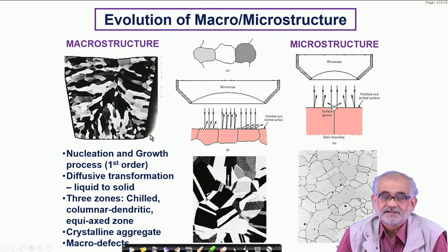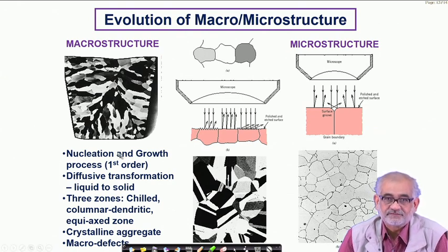And this hierarchy tells us that a given system like this may comprise a single or multiple phases, and also may comprise a single crystal in very, very rare cases where we create an artificial condition which allows only one single nucleus to grow and consume the entire liquid and end up being a single entity for the entire bulk of the solid that we are seeing.